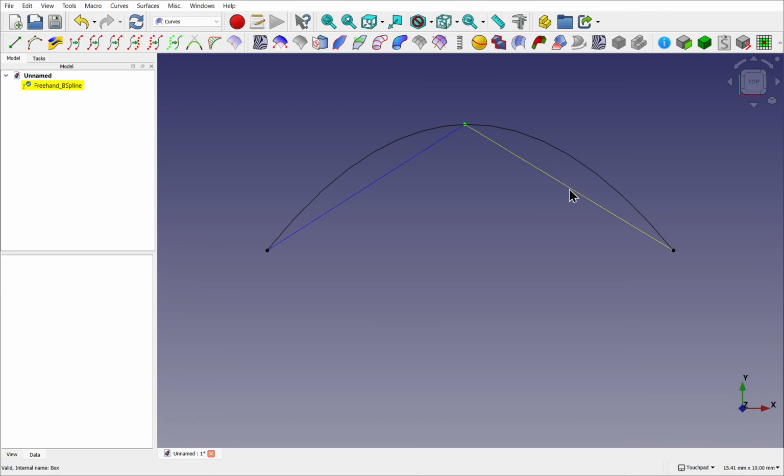These segment lines can be selected and moved as well. So I'm clicking and dragging, and you can see the coordinates on those points that connect that line displayed on screen and changing as we drag it about. And when we drag, we can drag this segment to where we want. If we want to be more accurate when we're dragging, we can select, say, this point, hold down Shift, and we can drag this at smaller intervals. And the same with the segments. Click the segment, hold down Shift, and we can drag that at smaller intervals.